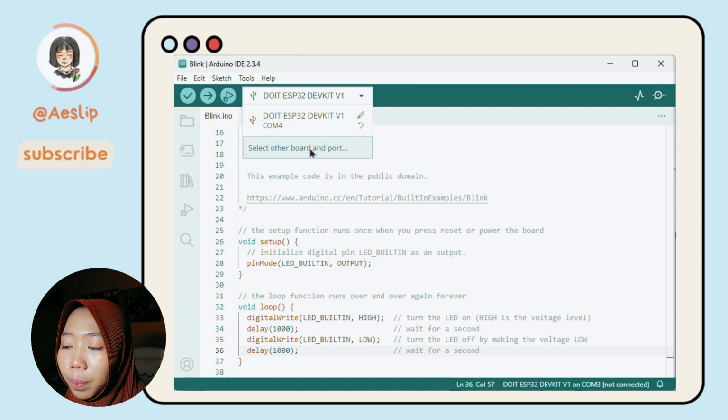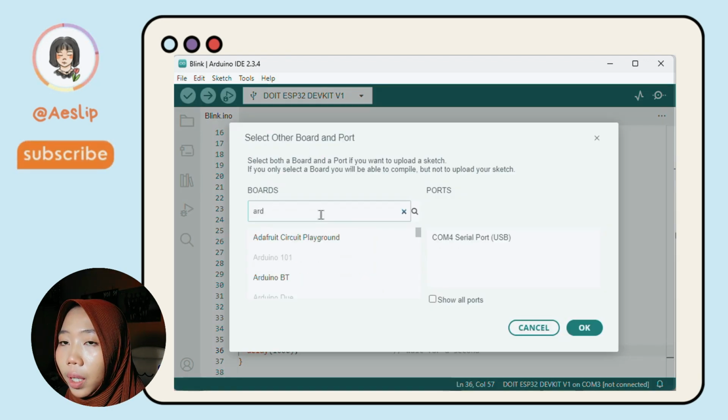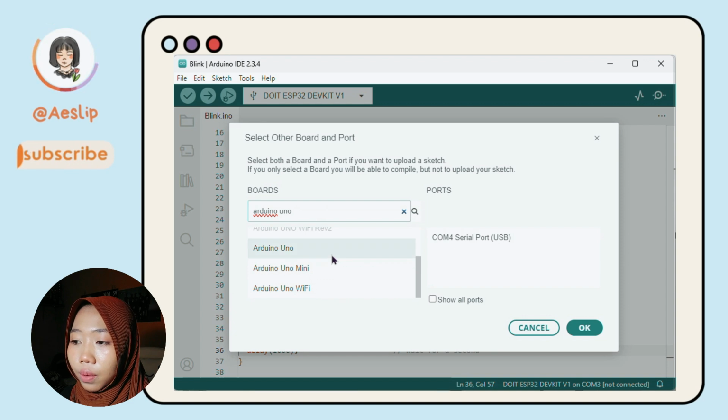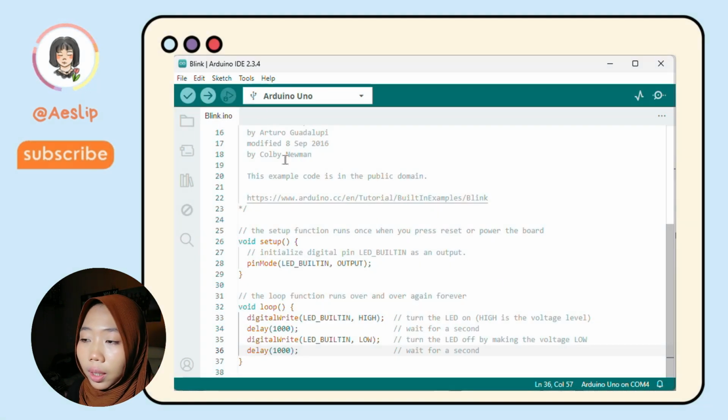Make sure the board is set to Arduino Uno and select the appropriate port. Click Upload and wait a few seconds. If it's successful, the LED on the board will blink every 1 second.